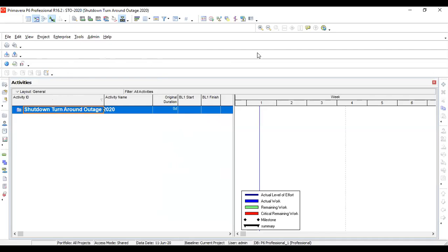I will share the whiteboard first, and then we will learn how this process flow diagram will go on. This time you have to click on Project in your Primavera, and once you click on this button, you will be given a drop-down window. In that window you have to click on WBS. Further on you will be given a WBS window. In that window you have to click on the top right corner of the screen. There would be one plus symbol. You have to click, and further customization I'll make you understand once we are on the Primavera 6 dashboard.